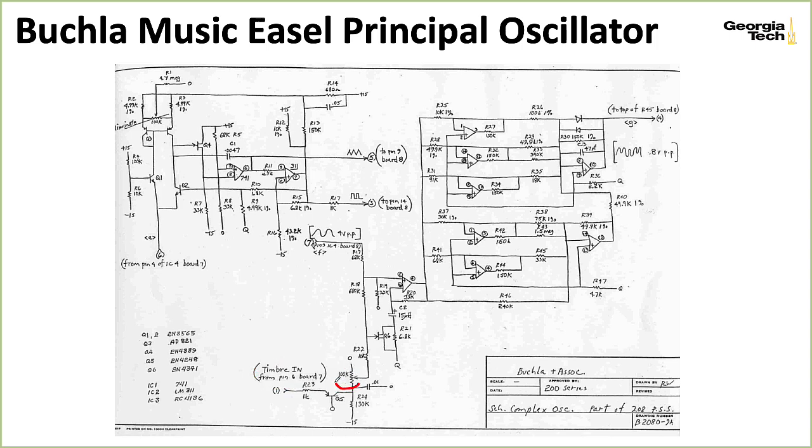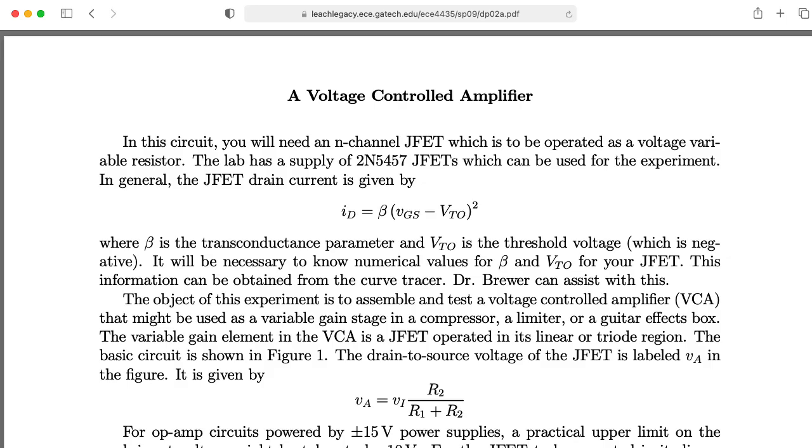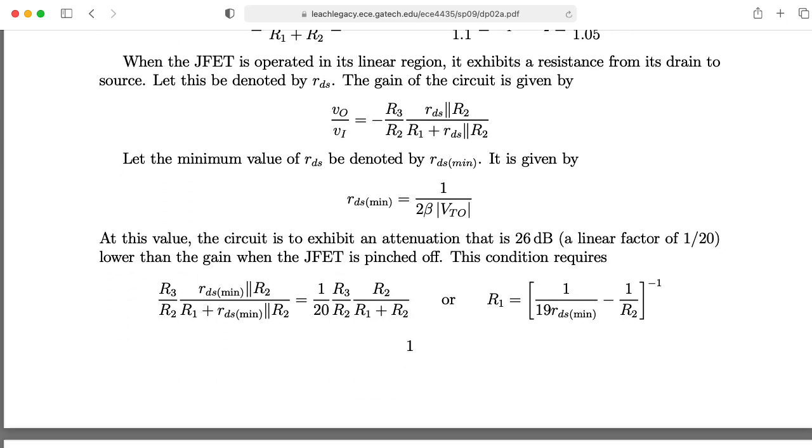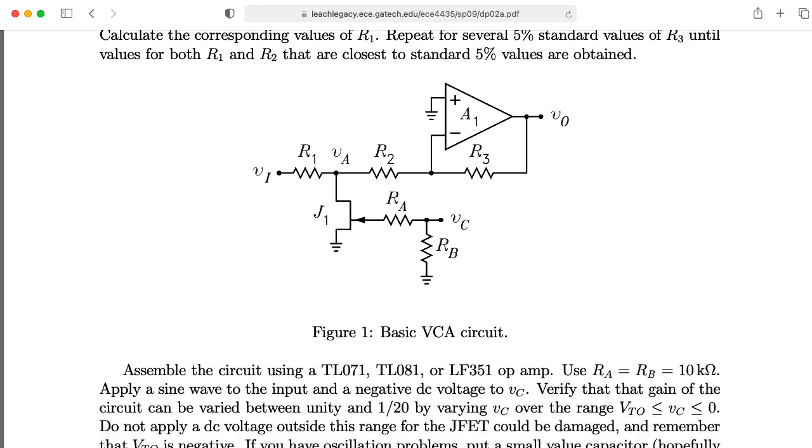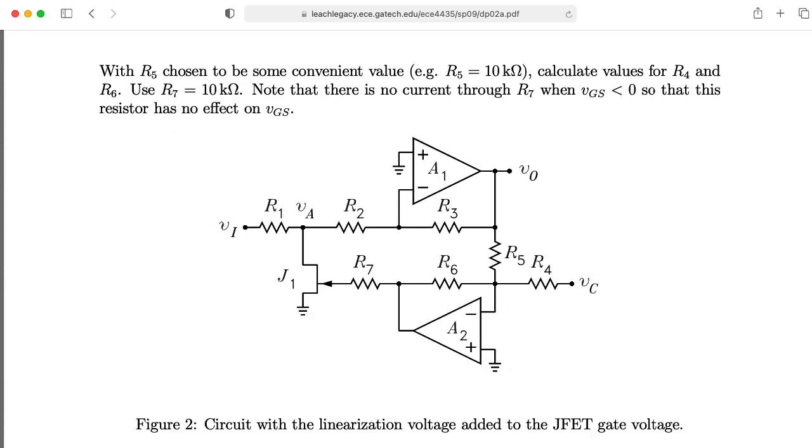And if I remember right, this is a trim pot. It's not a front panel control. The front panel controls are shown in another part of the schematic. A little bit of the sine wave is actually being added into the base here. And if you look up app notes about using JFETs as rough voltage-controlled resistors, you'll see that this is a thing you can do to try to linearize some of the nonlinearities inherent in trying to use a JFET in this mode.